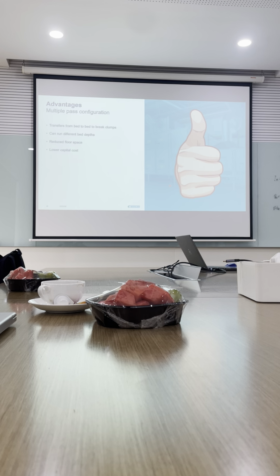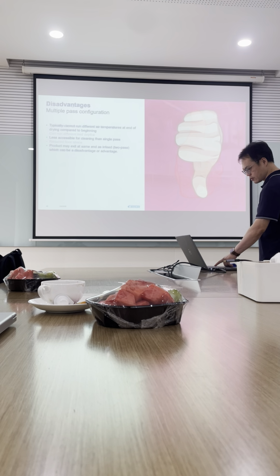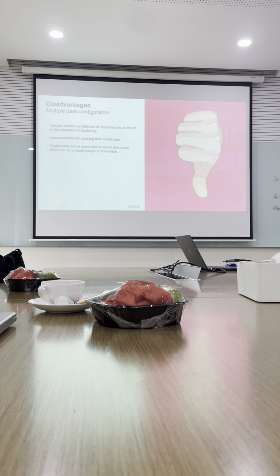We can run different bed depths and reduce the floor space and the noise control cost. The disadvantage is that it cannot run different air temperature at the end of drying compared to the beginning.